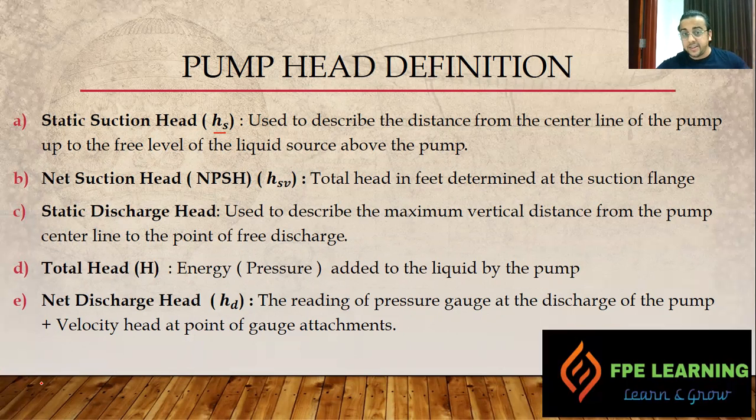So this needs to be understood carefully while designing your pump, because if you don't have enough NPSH available, and that required by the pump manufacturer in the data sheet, that minimum we need this much pressure at the inlet of the flange, and later on if you purchase the pump and at the site there are different scenarios, then trust me, at the end of the day you are going to regret those conditions. So that's a part of some other videos, we'll discuss that one.